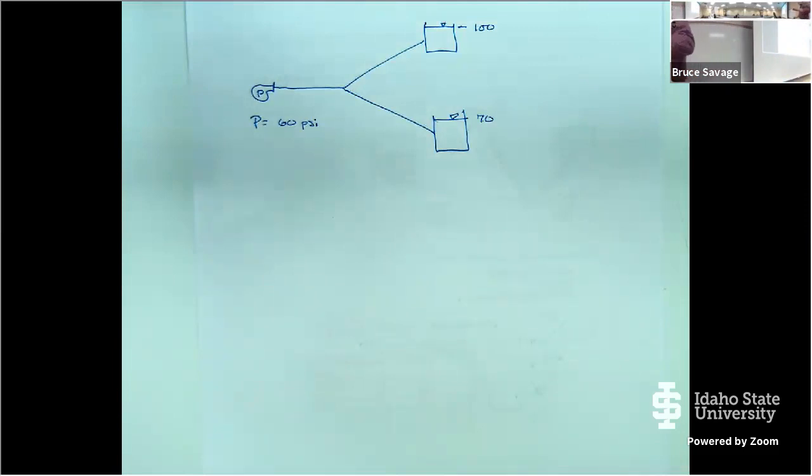And what I'm trying to highlight here is something that I've told you multiple times as well, is that reservoirs just represent energy at the location that it's at. So that pump is adding energy to my system, right? Obviously there's flow coming in somewhere to that pump, and then that pumps work in one direction, at least that's what they're supposed to do. So I definitely know that flow, if I call this 1, 2, and 3, and I definitely know that flow is going from 1.